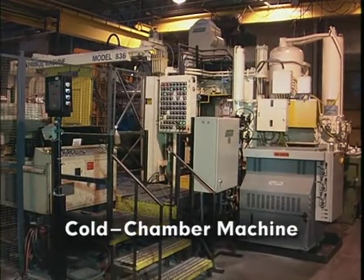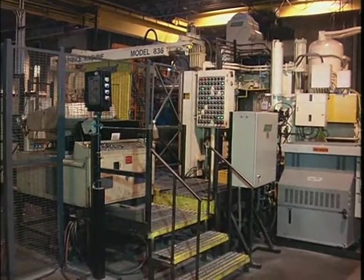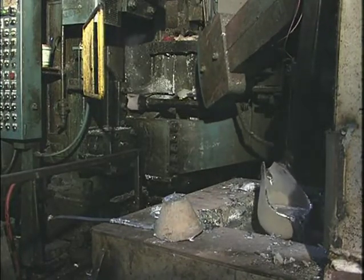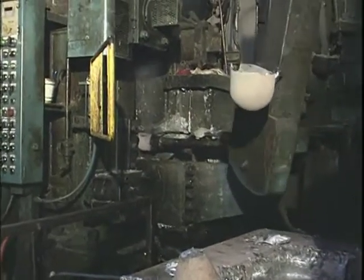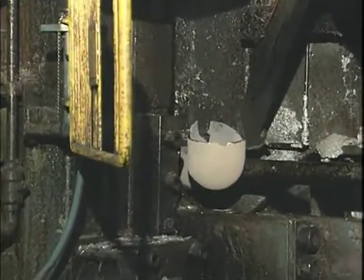The cold chamber machine is used primarily to die cast the aluminum, magnesium, and copper alloys. In the cold chamber machine, the charge is supplied by ladle or feed system from an external furnace source to a holding pot at the shot end of the machine. The feed system components are not submerged in the molten metal.